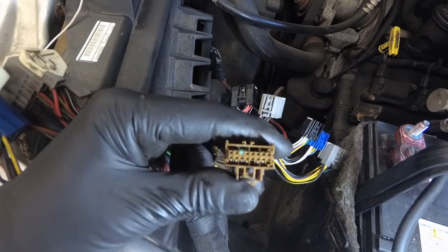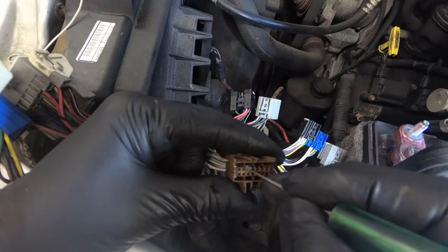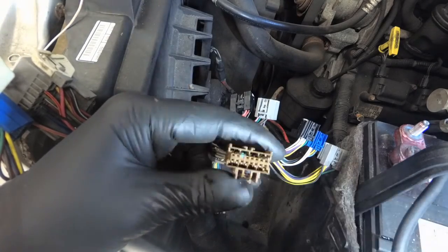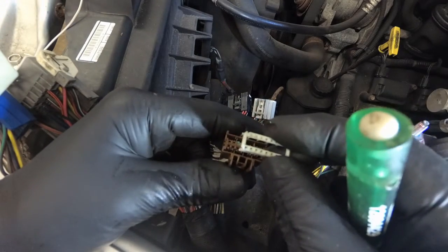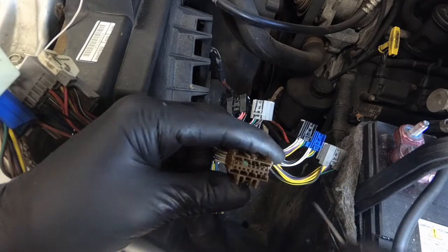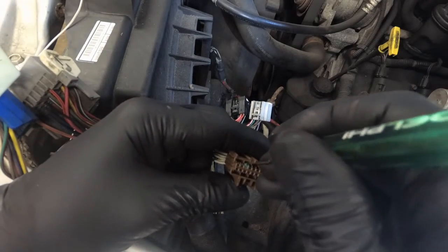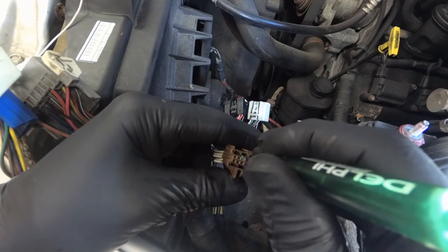So here you can see the connector that is on the truck has the same failed terminal, so we have to get this terminal out of here. Now there's a white secondary lock that you have to pry out, and then once you pry the secondary lock out, there's a little plastic release pin that you have to grab with a pick of some kind and pull off to the side while you pull on the wire.